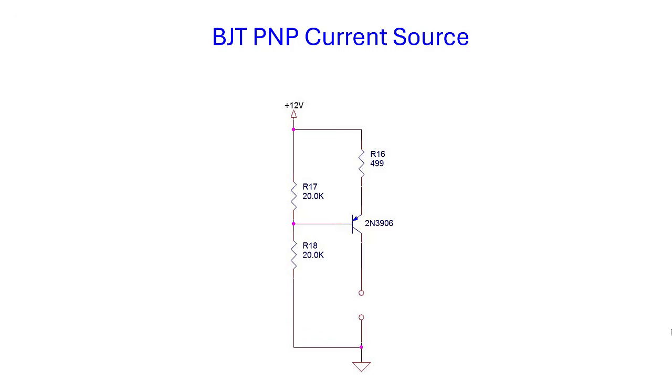Once you build the constant current source, you will use the digital multimeter as an output load in the collector. Be sure to insert the meter in series before powering the circuit to make your current measurement. This measured value should be very close to the current that you calculated.